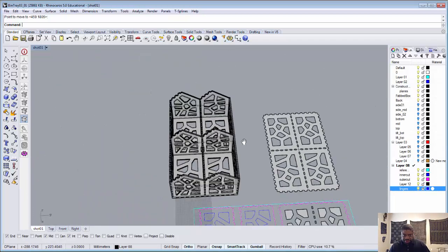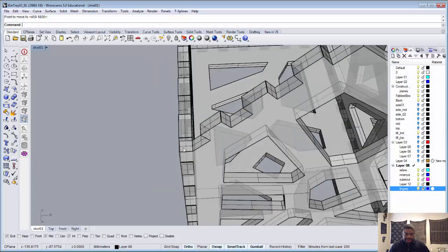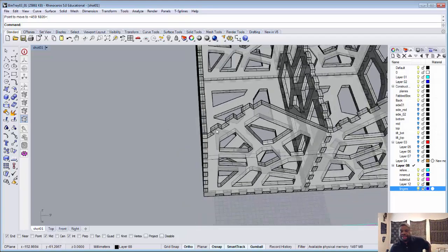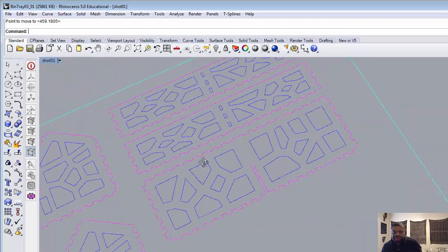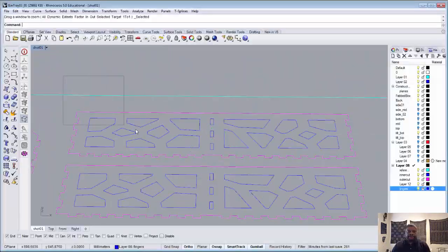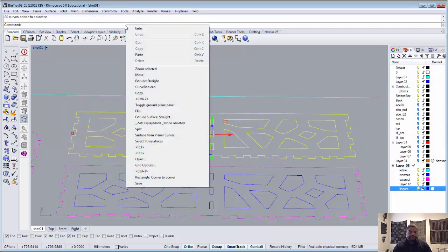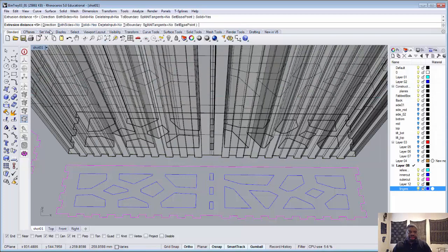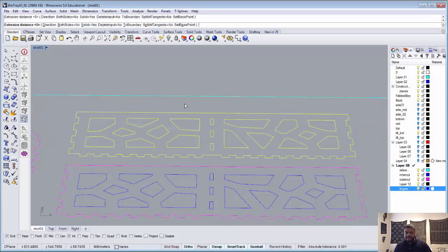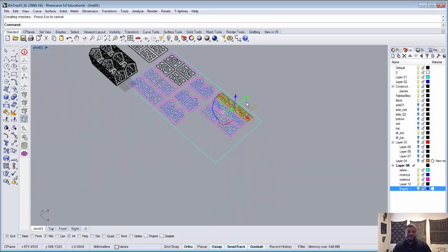Now the last pieces that we have to do is the pieces that attach here. Okay, and we're going to attach it here straight, then rotate it back in place. Okay, and so the first thing that we want to do is that we want to generate the slab. It's right here. Select this like so, and I'm going to do an extrude straight, solid, yes, the value set to 5. I think I've repeated that enough. Okay, and so now I have this,